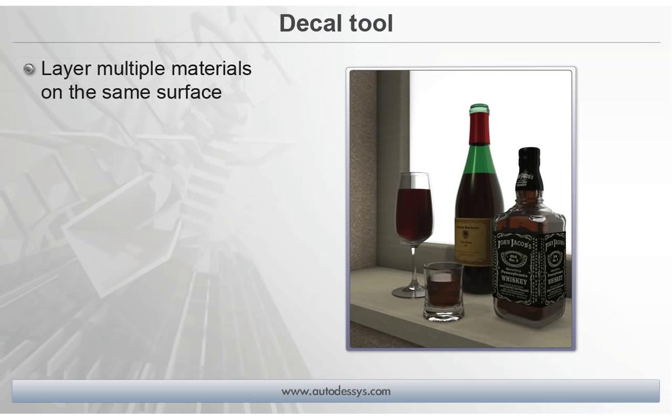The RenderZone plugin also includes a decal tool, which lets you layer multiple materials onto the same object. So not only can you apply it to single faces, but you can also layer up to 32 different materials on top of the same surface.